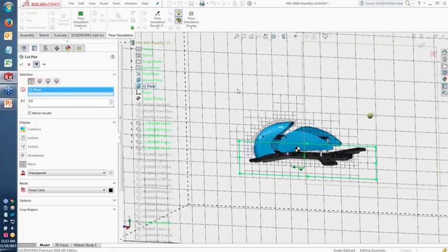And in the past, the only way to really get better refinements in those areas, which can be really important, the upstream and downstream of your craft, was to either refine the mesh everywhere, or you'd have to use some pretty advanced options like the solution adaptive meshing, which would automatically detect where you have discrepancies in things like the pressure or velocity results, and it would fill them in with more detail. But again, the solution adaptive is a pretty advanced option, which required a lot of knowledge about the mesh to get to work properly.